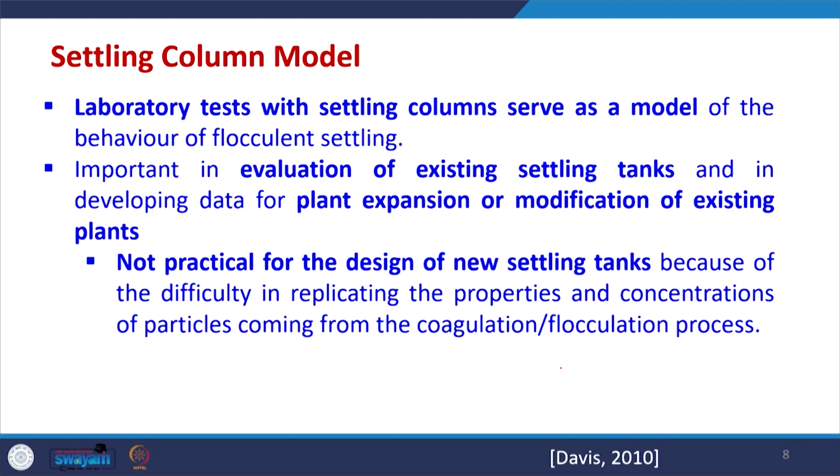Now, this laboratory test method is more correct if we have to evaluate an existing settling tank, if we have to optimize it, or if similar water is there and we have to go for plant expansion. So, this is more useful, and not very practical for the design of new settling tanks. It is better to go for the other methods, some of which have been discussed, and some more will be discussed.